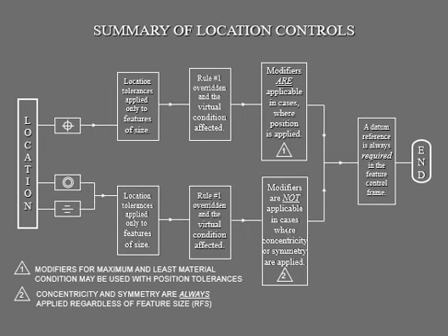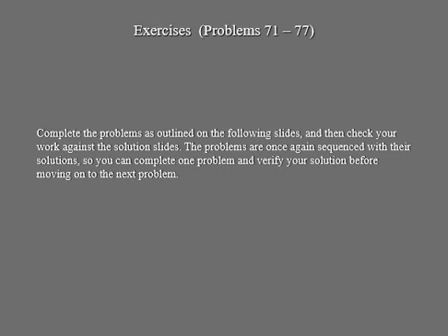In cases where concentricity and symmetry are applied for location, we go the same way: your datum reference is totally needed in the feature control frame to control these location tolerances.